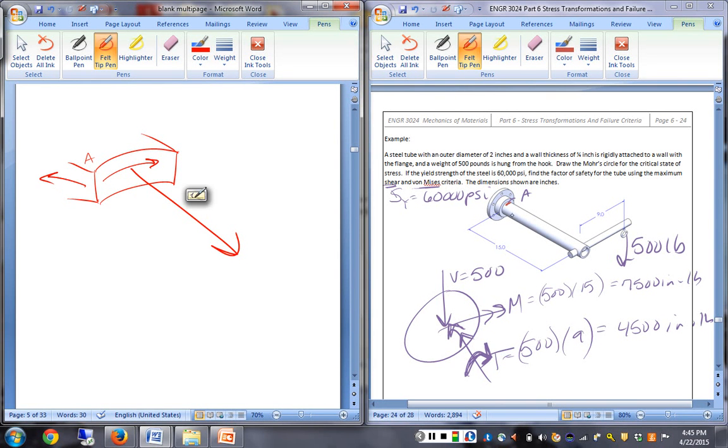If I instead look at a section underneath at 6 o'clock, what is that one going to look like? It's compressive, and these values are 13,969 and 4191. So I would have 13,969 into the surface, and I would have shear going the other way.